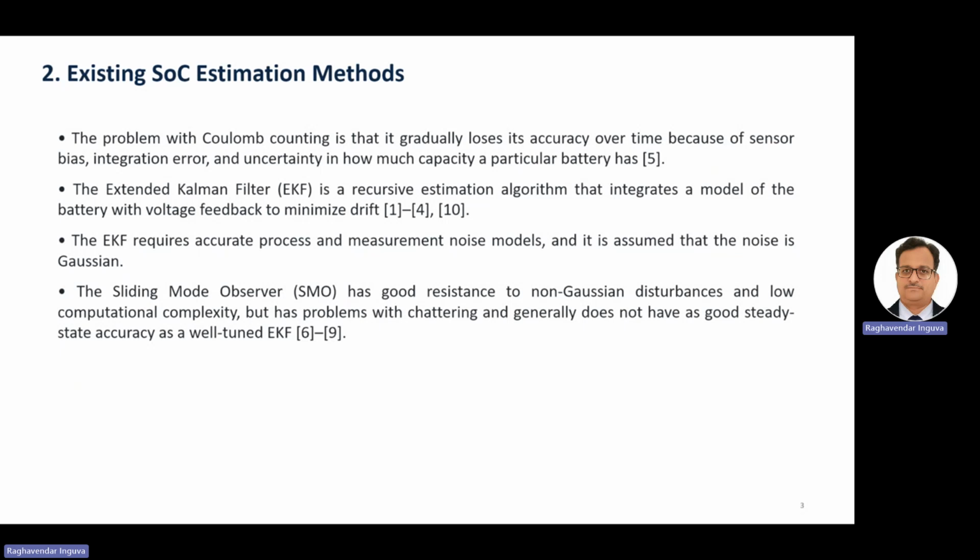Chattering is going here and there, left and right, while estimating SOC. So it won't usually give a good steady-state accurate result like EKF, but during dynamic and harsh conditions, SMO will give you a good result, if not accurate, where EKF usually fails.